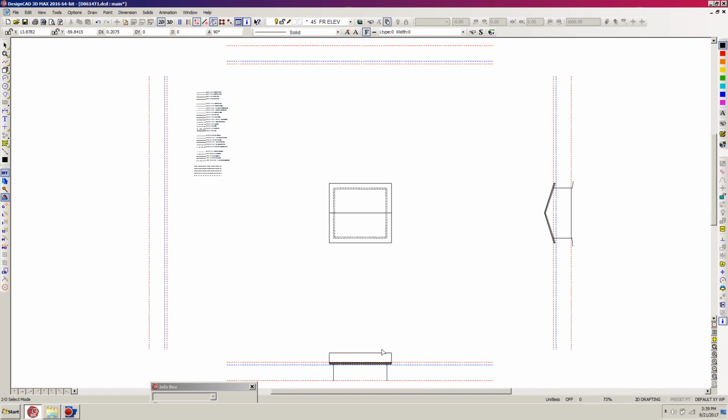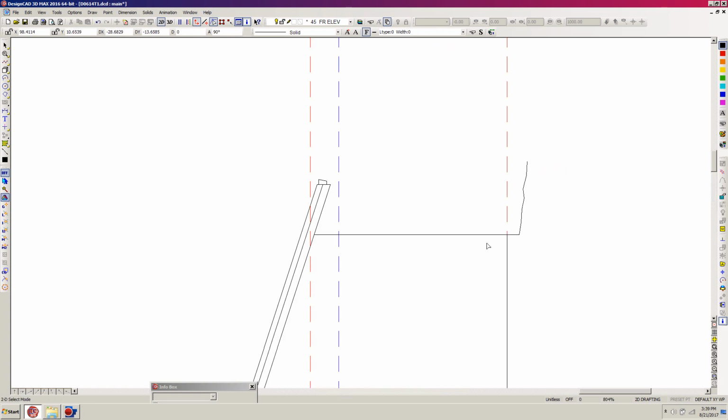One of the things that I should have done was to use my old grade lines. But here's what I'm going to do. I'm going to hit Z for zoom. I'm going to select this grade line here just by right-clicking on it. And I'm going to set a handle for it right at the juncture of the floor line and the wall line. So I'm going over here to set selection handles, clicking on it, going over here to intersect 2. Over at the left-hand side over here, you see the intersect 2. I'm going to click on that.